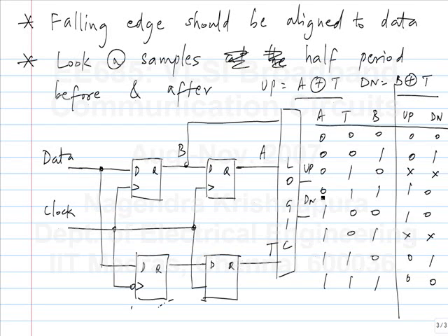So basically, the output of the phase detector is persistent for one symbol period. After that, you get the output of the next transition. So corresponding to each transition, there is a phase measurement. That phase measurement lasts for one symbol period. So during the next symbol period, you get the phase measurement corresponding to the following transition. If there is no transition, you will get 0. That is no information. If there is a transition, it gives you up or down depending on what the phase difference between clock and data was.